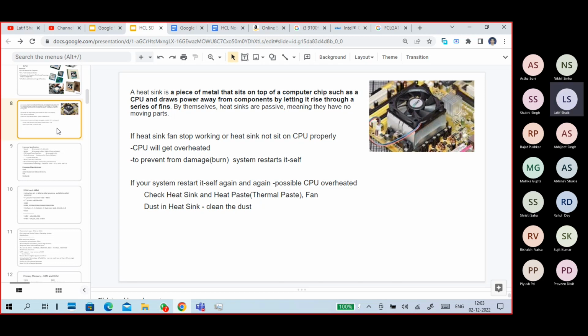So what will it do? It generates a lot of heat, because you are blocking the vents. The heat is harming you. Plus, because of that heat, your battery will be damaged and it will start generating even more heat. Because of all this heat, the computer's internal components will be damaged, not only the processor but other small components as well. The plastic will also be damaged.